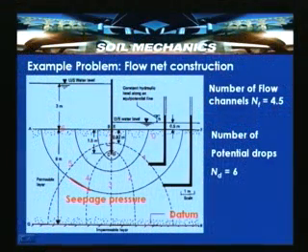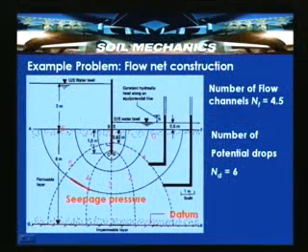So, the head loss which is occurring, for example, if you consider equipotential line 5, the potential, that is the total head, at this point and any point along this particular line will be the same. But the potential difference, the drop between 5 and 4, occurs because the flow is taking place over a length of distance between 5 and 4, and then it reduces to a drop.